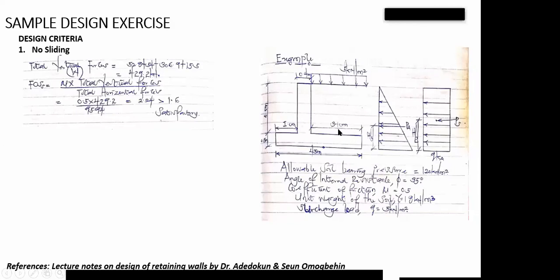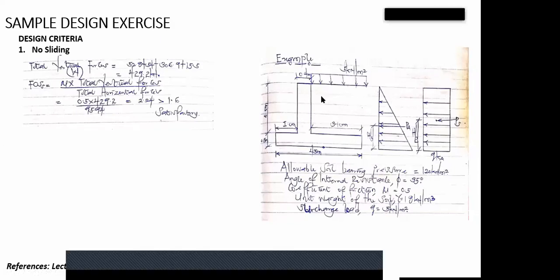But what makes your horizontal forces? Only 2 things make your horizontal forces, and those 2 things are just your soil and your surcharge. Please take note of that. Now, we've gotten our vertical force.